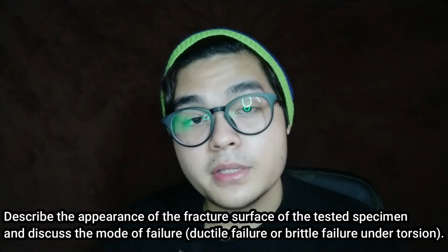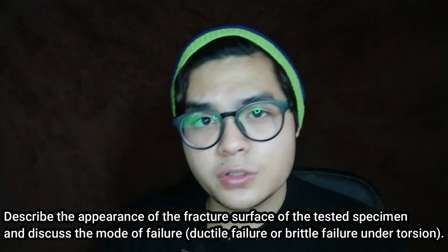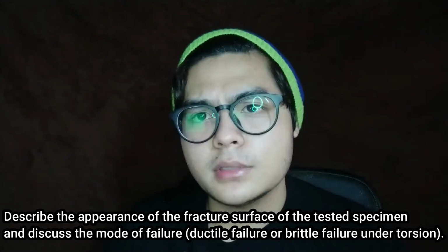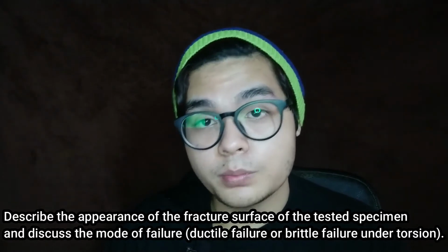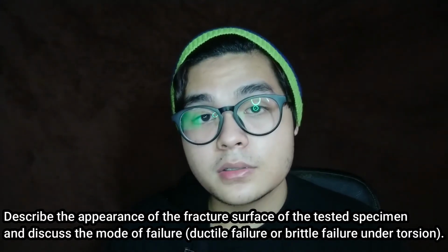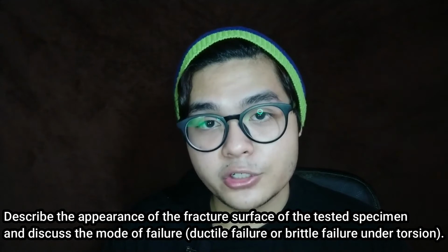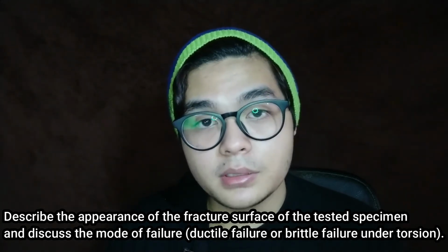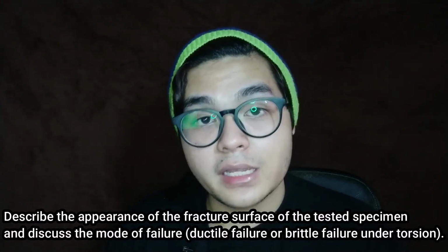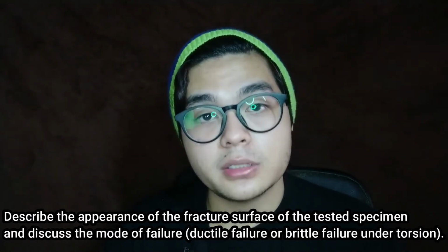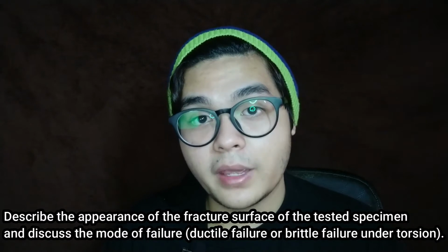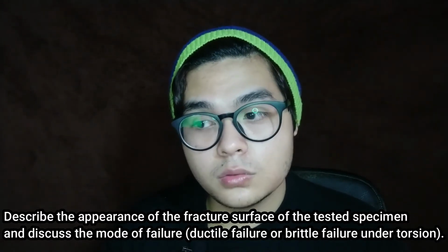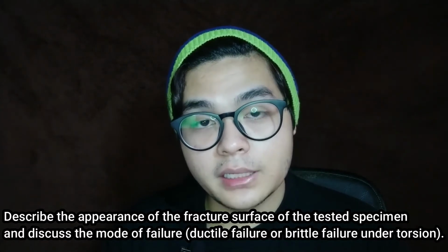The fourth, based on the appearance of the fracture which is twisted with an angle, the mode of the fracture is ductile for steel and for brass is brittle. This is because the appearance of a ductile fracture is relatively smooth and has spherical dimples of micro voids that initiate the crack formation, while brittle is shaped with angles with a fracture of faceted texture due to changing orientation of the grain cleavage planes.